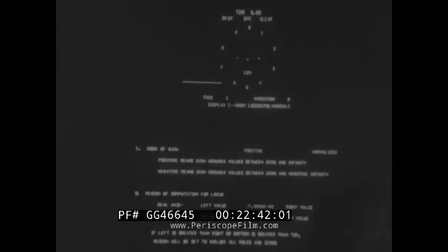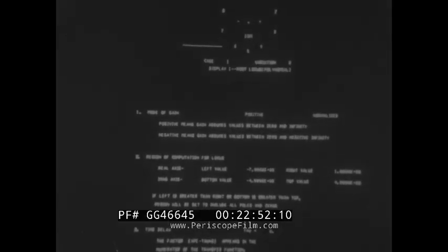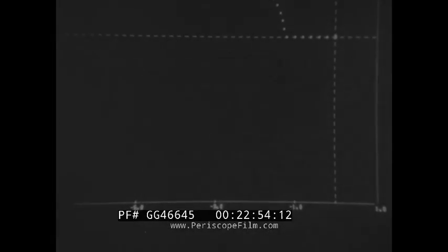I have now decided to utilize the other graphical method, root locus, in order to completely understand the response of this system. This method uses the same transfer function, but produces the plot of the roots of the characteristic equation of the closed-loop system as a function of the gain. After entering values which will define the boundaries of my root locus plot, I direct the program to compute the locus and display the plot.